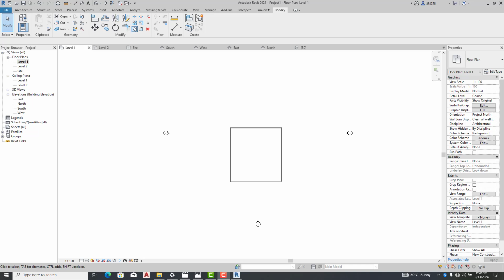Like other basic elements in a building model, walls are instances of predefined system family types, which represent standard varieties of wall function, composition and thickness. You can customize these characteristics by modifying a wall type's properties to add or remove layers and divide them into regions. These are the basic things.